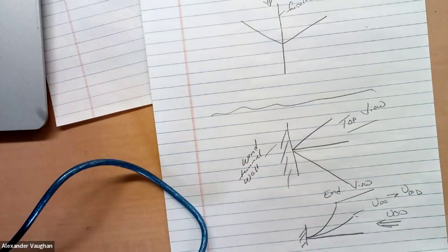Dr. Dowell, I have a quick question. Okay, go ahead. What are some advantages of a forward swept wing? It's principally the aerodynamics. If I recall correctly, and it's been a while since I've thought about it, there's flow separation. This was going to be a fighter-like aircraft, so it's going to go through fairly severe maneuvers. There was concern about flow separation, and the flow separation pattern is more favorable on the forward swept wing than the backward swept wing.